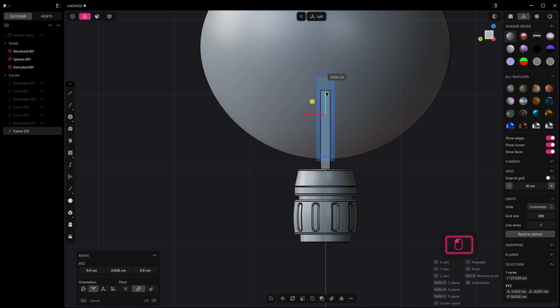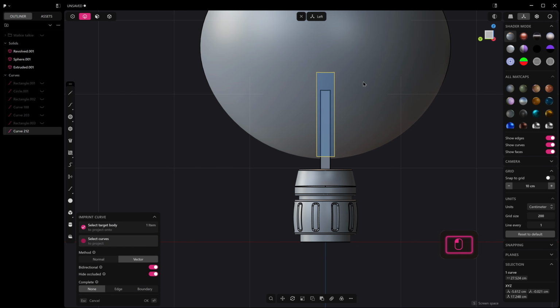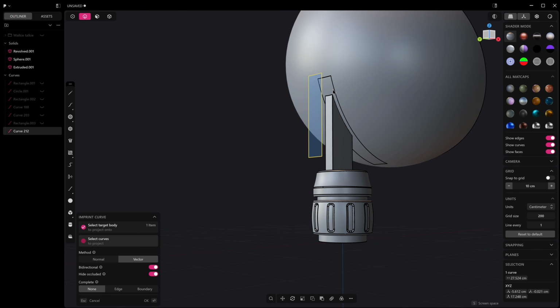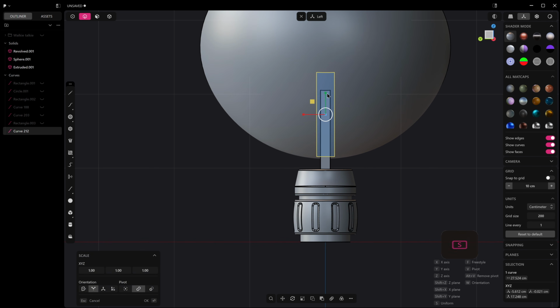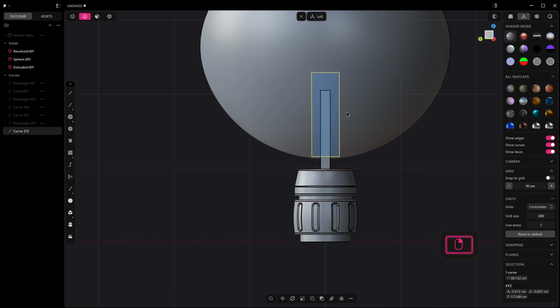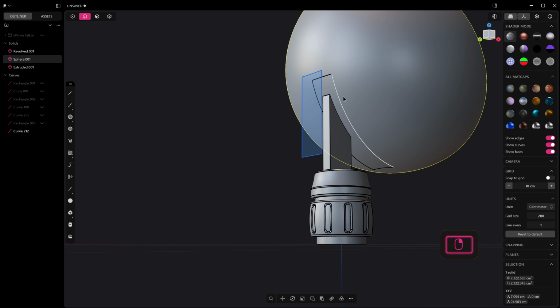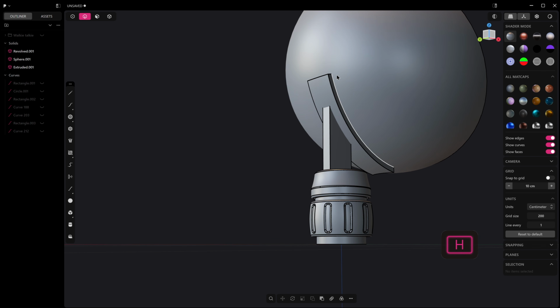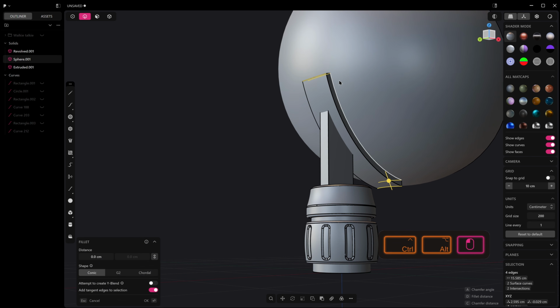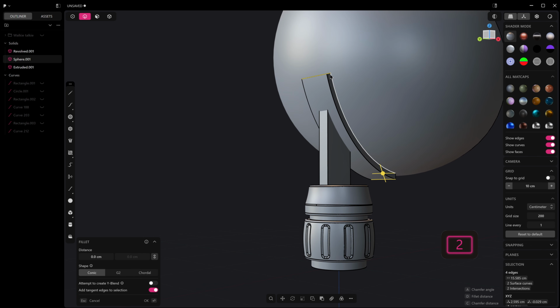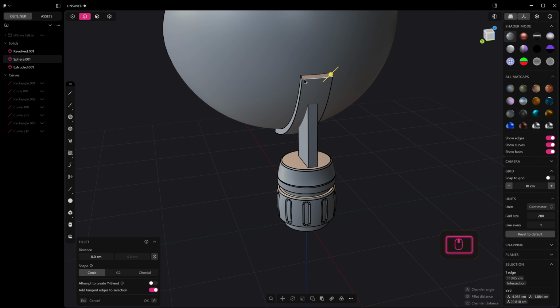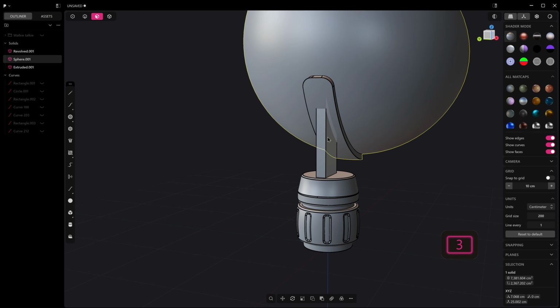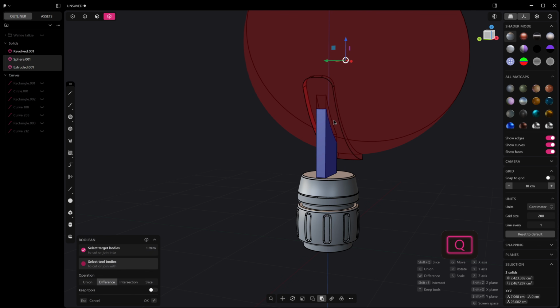I'm going to press G. And I'm going to press Shift I and imprint it and see how that works. Okay, I want it to be a little bit fatter than that. So Control 3, S scale, and now we can try and imprint that. So Shift I. And I think that's a nice imprint. And then what we can do is we can actually bring that out like that. We can hide our curve. We can give this some nice rounded bit there. And we can join this to this. Q, Q.